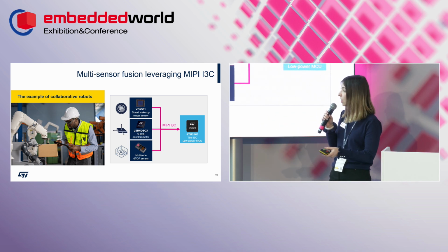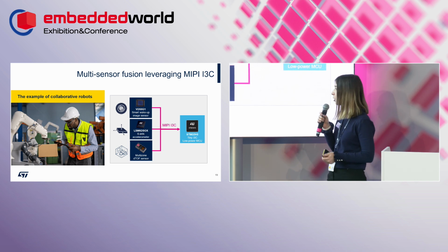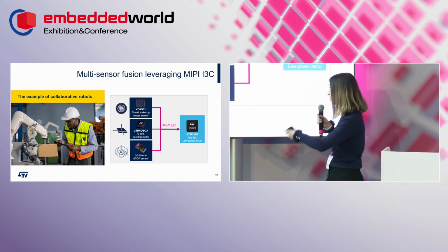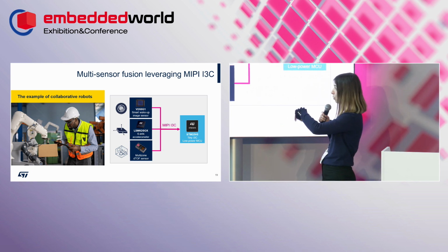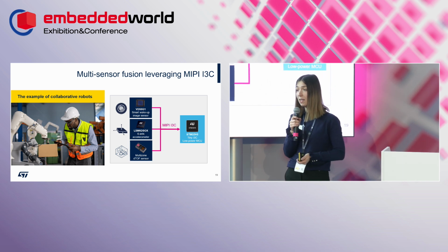And this is very nice with the I3C because they implemented a lot of features very useful for multi-sensor usage, such as the inbound interrupts. So in the communication protocol, you don't need an additional GPIO. You can notify of an event and pass the master control to another sensor. The I3C also supports dynamic addressing.